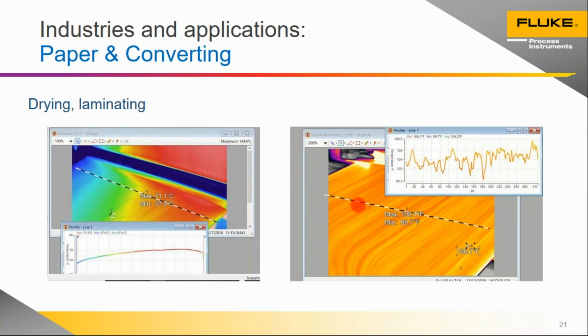This line also employs some specific direct thickness measurements using totally different technology. But one thing we're able to learn from the customer is we're able to infer the thickness of the material because it's extruded out at a much higher temperature, about 600 degrees Fahrenheit. And so when it's applied and goes over a cooling roll, even after that point, and it comes by where the imager is, you still have a big difference in temperature, a higher temperature where the material is a little bit thicker, and a cooler temperature measured where the material is thinner. And so this gives them a proxy very quickly for the thickness that they're laying down across that substrate.